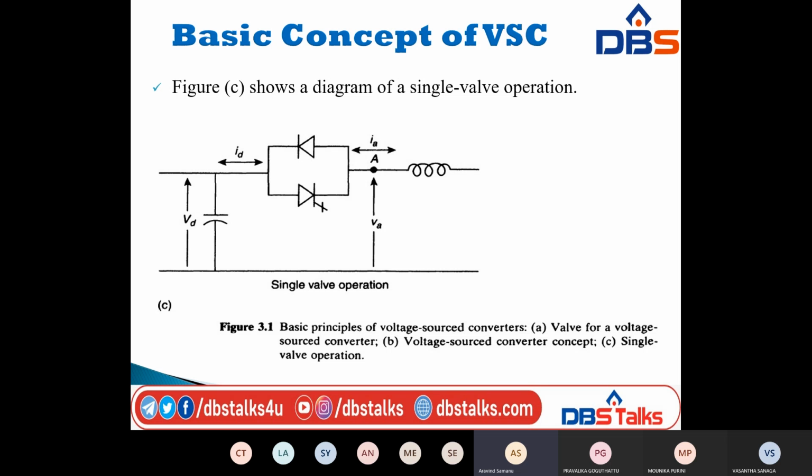Here we have the AC voltage, AC current and an inductor, or reactor. Observe carefully. When the turn-off device, that is the thyristor, not diode, thyristor, is turned on, the positive DC terminal is connected to the AC terminal A, and the AC voltage would jump to plus VD, the positive direction of VD.